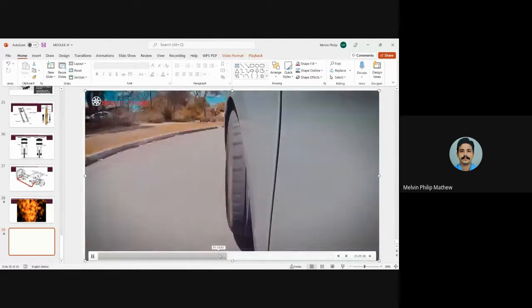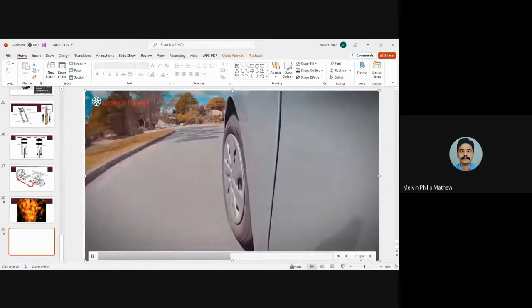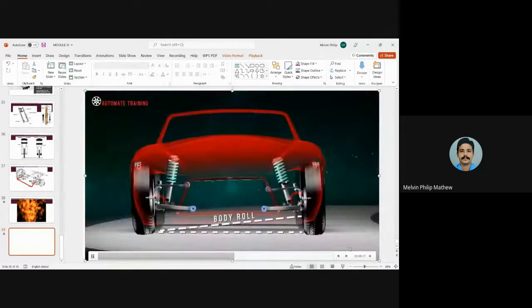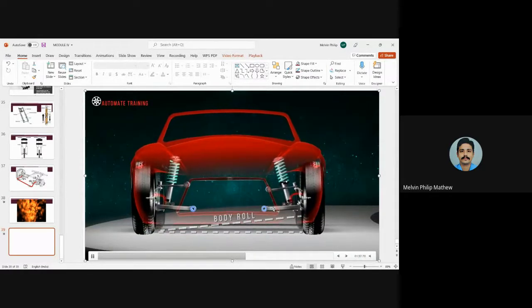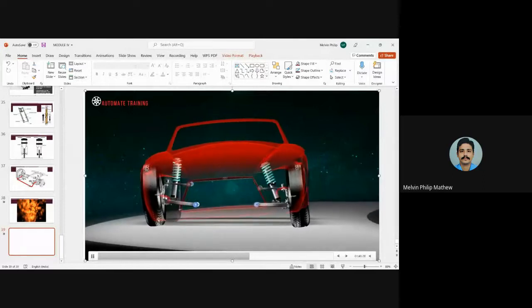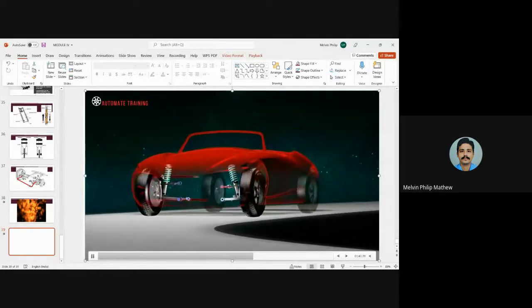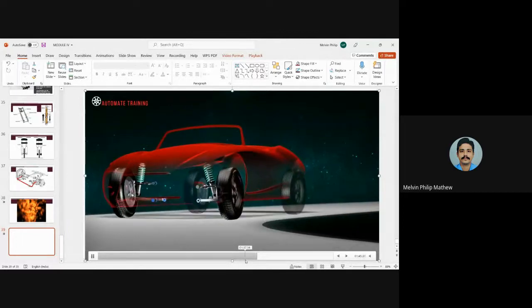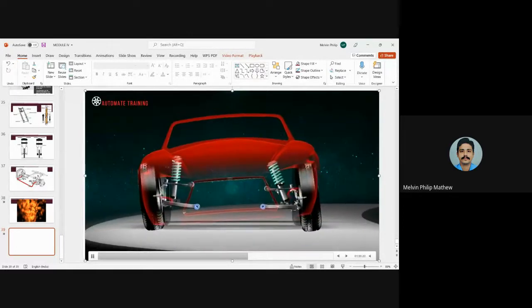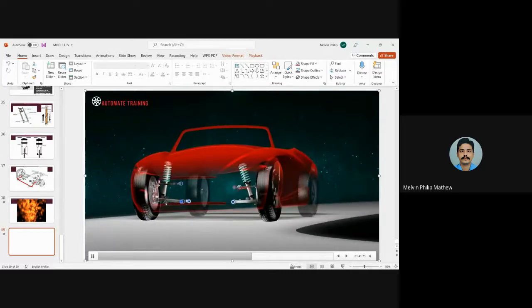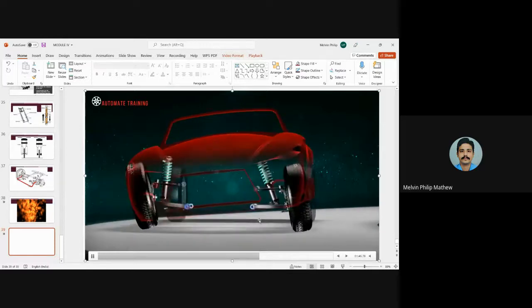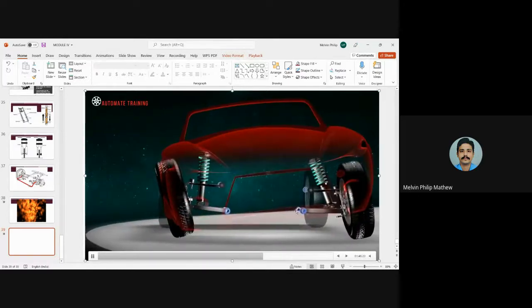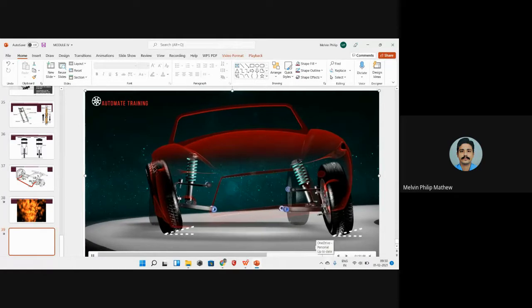You can see while taking a roll, this is our anti-roll bar. So when the body is rolling, one wheel compresses, another lifts. So the anti-roll bar moves accordingly to provide a sufficient twisting moment, or to provide the inner wheel to touch the ground. It converts that twisting moment into a force that pushes the wheel downward.